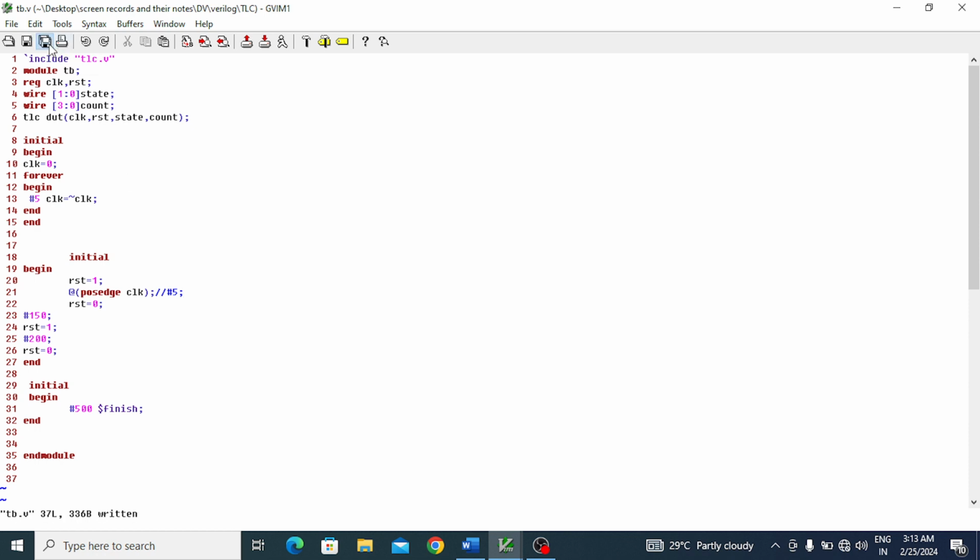Anything is okay. Suppose if you write always before this at-the-rate, the reset would become 0 at every positive clock edge. I don't want to make reset 0 at every positive clock edge, I just want to release the reset at the first clock edge.